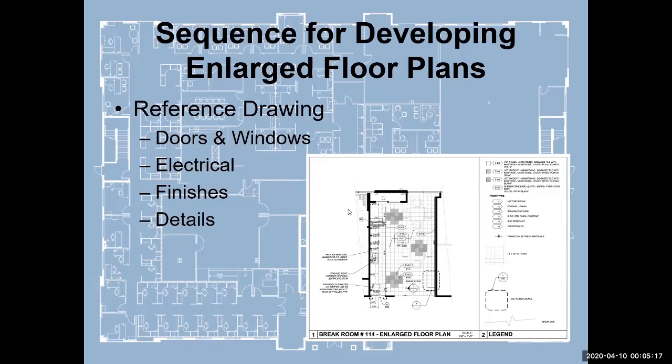So in this, we have dimensioning, we have noting, we have detailing, and it's all pretty ordered. There's not a lot of conflict. So you need to try to pay attention to how things are placed and look for conflicts, because if a contractor can't read the drawing, he's likely to get it wrong, and he'll use the drawings as his excuse for not doing a good job with the design.